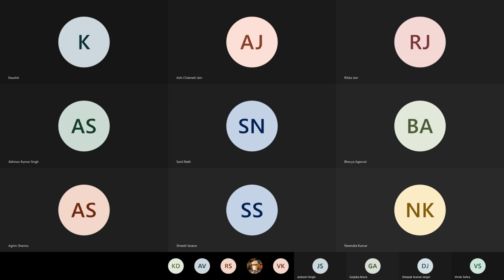Then find the standard heat of this combustion reaction at 298 from the heats of formation, and then heat the products to 533 Kelvin: the integral of n Cp dT for each product, summed over all products, from 298 to 533.